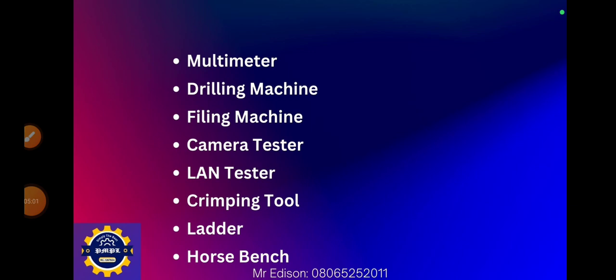This is very simple and negligible, but it can keep you for days if you are not versed in using your tools. I have done installation where cable got caught inside. You continue to trace and trace, you won't be able to find the fault. Until I ran continuity tests, I discovered that the cable was caught inside from the point of manufacturing. So you need drilling machine to bore holes on walls where you pass your cable.